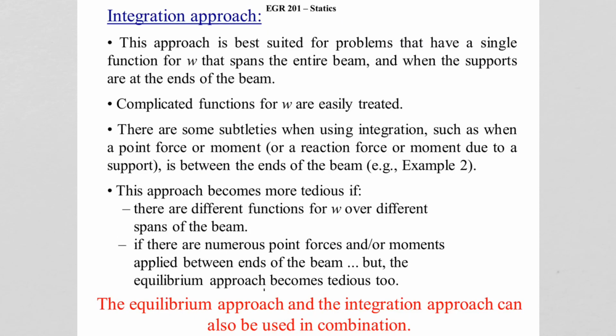The integration approach is best suited for problems that have a single function of our distributed load that spans the entire length of the beam, like the example we just did. It's good also for complicated functions of w(x). It can be easily treated through integration, but there are some subtleties when, using integration, we have point forces and things like that. It gets to be a little more complicated.